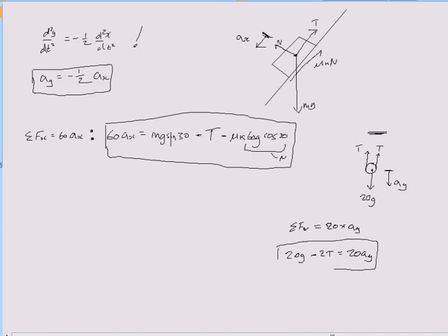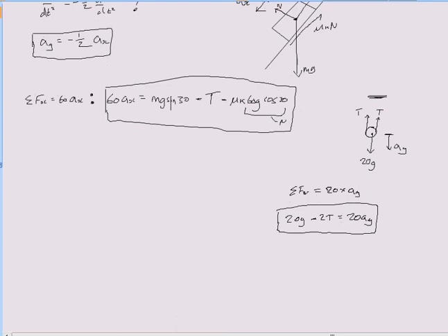So we've got 3 formulas and 3 unknowns. We've got 3 unknowns, ay, ax, and T, and we've got 3 equations. If we manage to plug them all in, we'll be able to solve this beast. So let's try and do that real quick. Let's first try and eliminate T, because that seems to be the biggest annoyance right now, even though you could eliminate whatever one you like first.